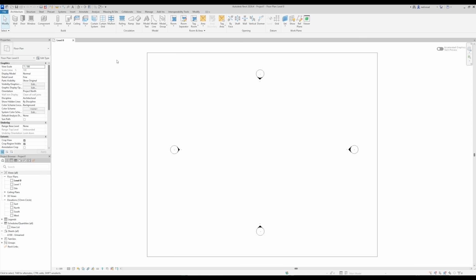So now we are in the main interface of Revit. At the top is our quick access toolbar, where we can access our views, section lines, dimensions, text, usually quick commands, by just pressing those buttons. Over here is also our toolbar, which is sort of the meat of what makes our project, from modeling to annotations. Over here is our properties panel. Similar to Rhino, we can see the data information of, let's say, an element. This is where our parameters are set in Revit, as well as our views when we want to model.